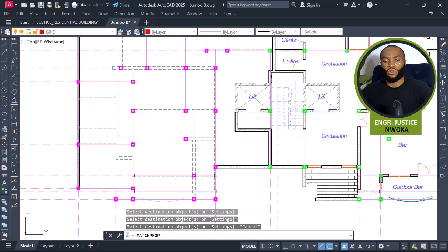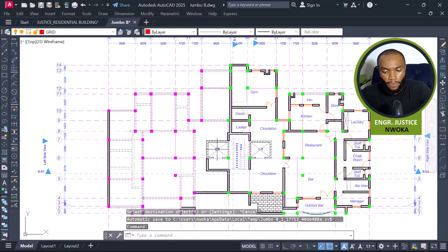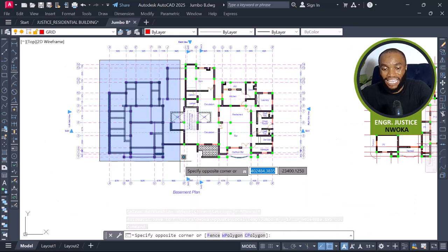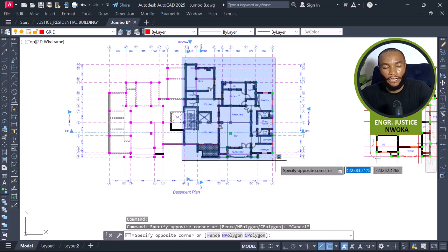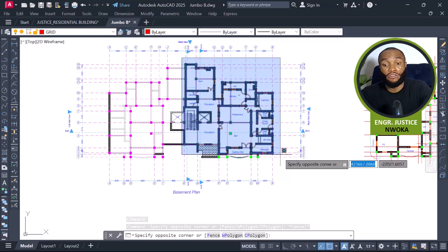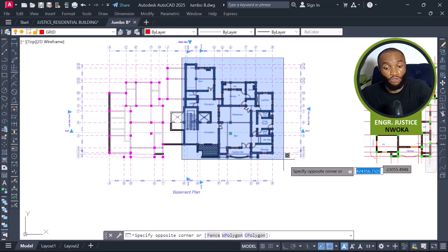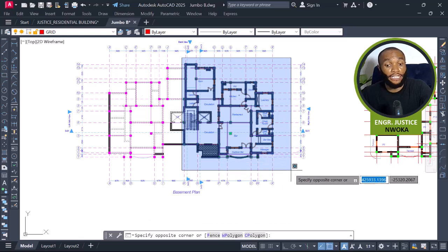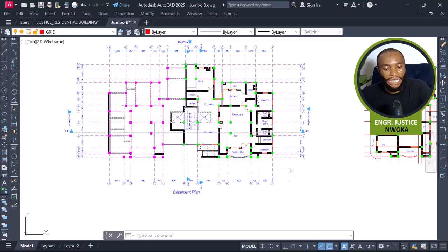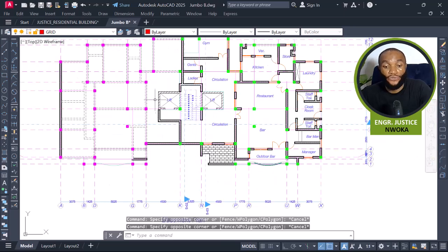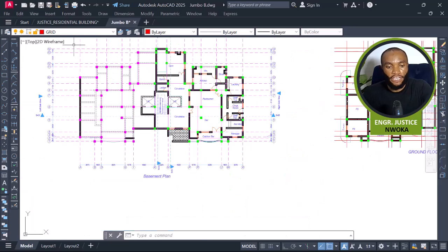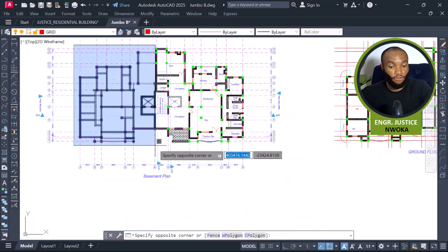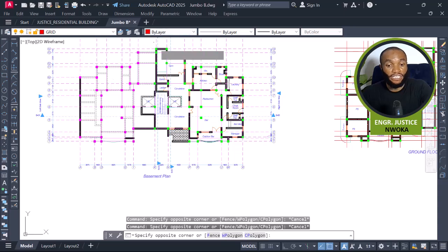Now because we have a basement, the sand here is stable, but here there is a slope which we are also going to dig. We are going to do some digging here to get it right. So in that case, there will be a retaining wall to serve as an embankment, because this soil here is not disturbed, but this soil here will be disturbed because of the basement.